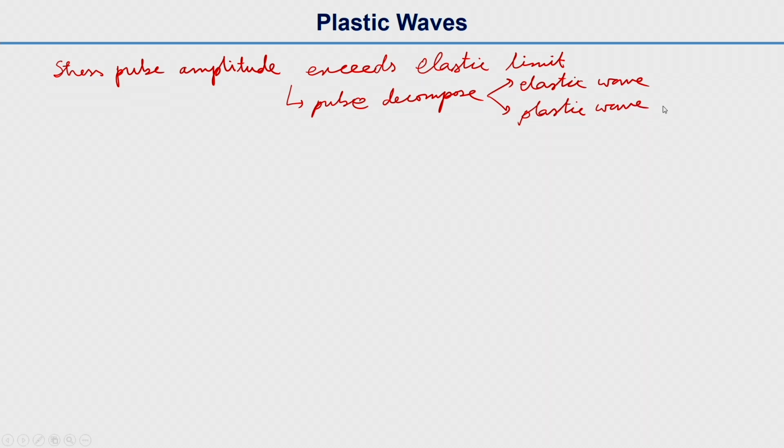We know that when a material is stretched beyond a limit, that is the elastic limit, plastic deformation happens to the material. Similarly in this case, when we have dynamic loading, if the stress pulse amplitude exceeds the elastic limit, then this wave will be decomposed into an elastic component and a plastic component.